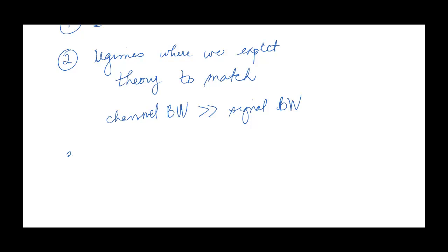Another tool that you can use is the Q-factor prediction of bit error rate. The relationship between the bit error rate and the Q-factor, which we've seen, is valid in the case when the noise is Gaussian. So one thing you can do is calculate the Q-factor, and then based on that Q-factor, calculate what the bit error rate should be, and see if that deviates from your simulation results. If it deviates from your simulation results, you would conclude that the Gaussian approximation is not valid, for instance, if intersymbol interference was present.